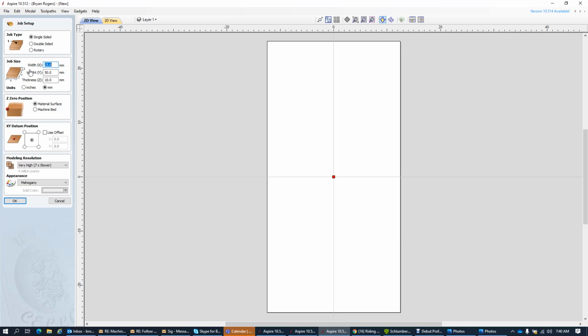So all I want to do is set this file up to where you can put the center of the bit somewhere, making sure that the orientation is correct on your knife handle or just a piece of wood, and it will start as the center. And that's what this red dot is. Think of this red dot as the 0, 0 position when you set 0, 0, and 0, meaning 0 X, 0 Y, and then 0 surface, meaning surface of the material.